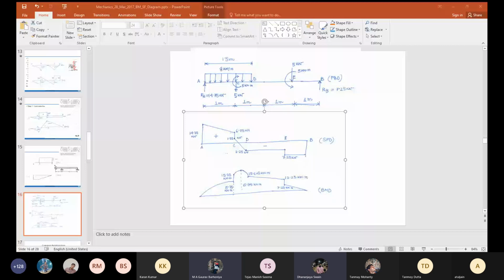The CD part is coming because when you are drawing the bending moment diagram, as I have shown in the red sketch that I have drawn, there are counterbalancing factors. Some are leading it to increase, some are leading it to decrease. Once the bending moment which is having negative value starts having a dominant effect, it will start to decrease. If I draw this section, how many terms are there for the bending moment?